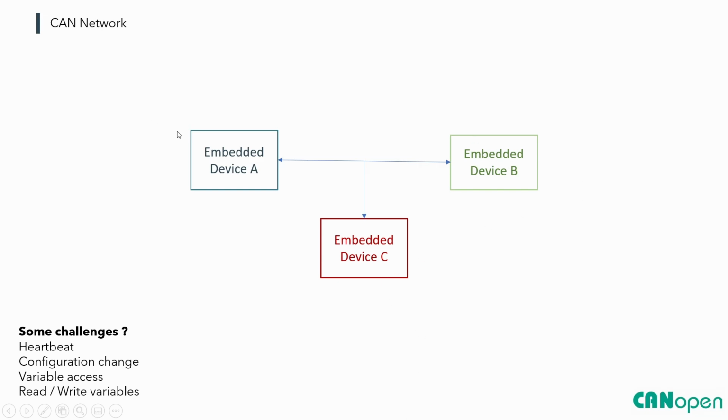Then how do the others know about it? Okay, we change the scenario: not on startup, but every 100 milliseconds, let's say, we transmit a packet, let's call it a heartbeat, and the others will know about it, and when they don't receive that heartbeat for a while, they know that device C is not on the line. That works as well. But then we have to write all this code for each of these devices, right? So you see the point, it's getting a bit complicated.